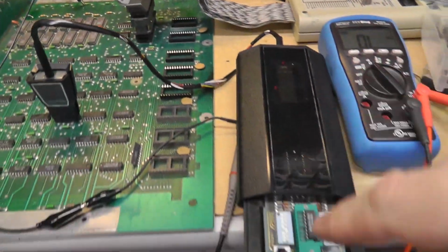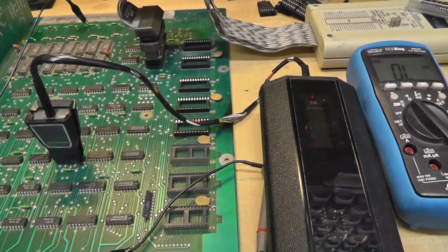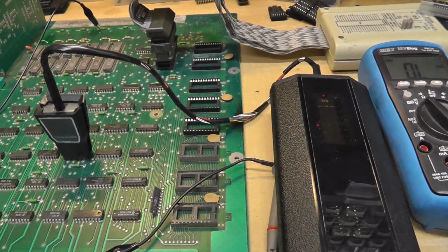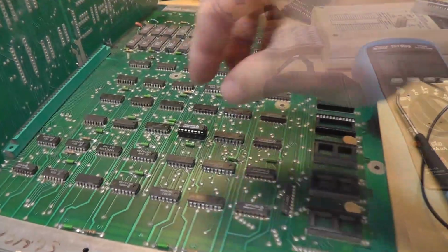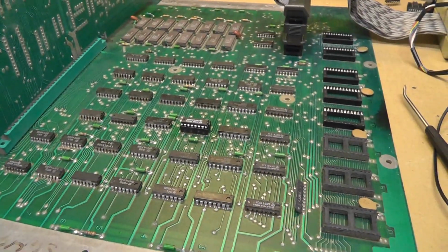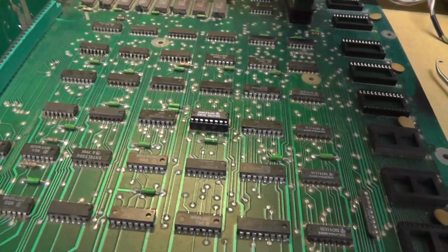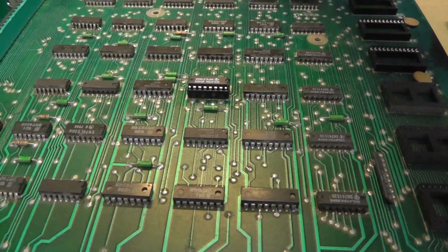Yeah, so I put it in my logic comparator. It definitely shows pin 13 as being bad. Doesn't mean that it's bad, but I think we're on to something. Let me go ahead and swap that out. Alright, I have the 166 replaced. I don't know if that was the issue or not. It could have been just corroded legs not letting me get a good logic comparator reading on it. And that looks like that might be the case because it's still white.